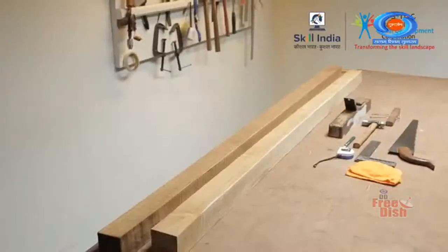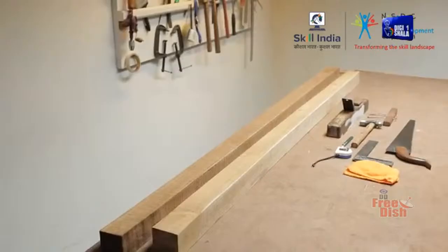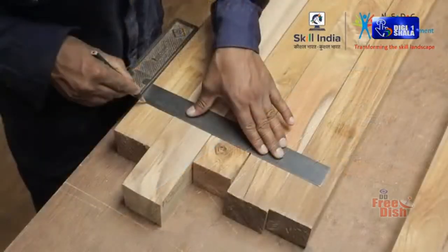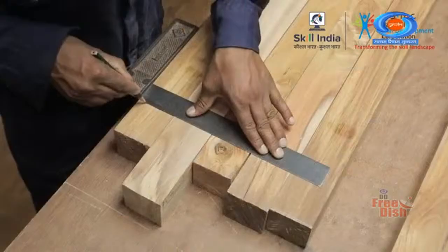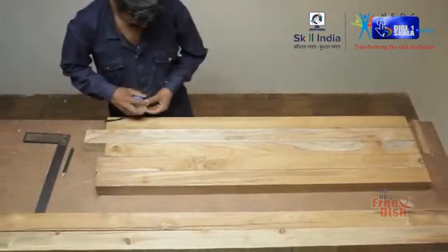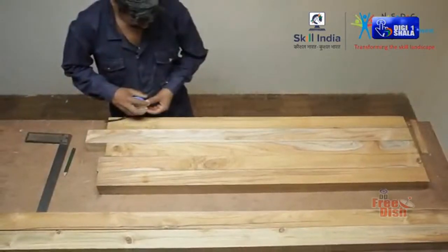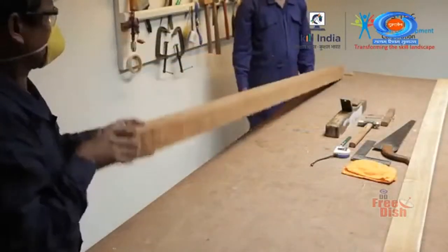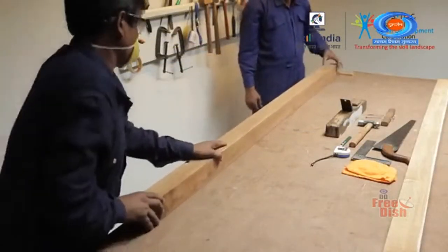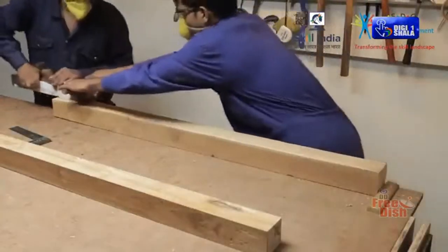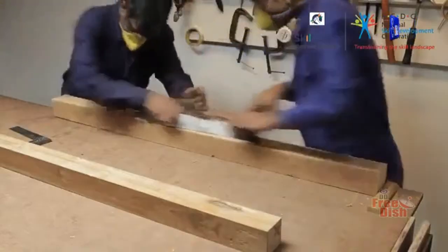Now that the preparation is done, it is time to get started on your workpiece. Before you start to cut down the parts for your partition, you must plane all the wooden pieces and bring them to the required thickness and width. Select the side free from blemishes and knots. Use a jack plane to smoothen the face side and face edge flat.